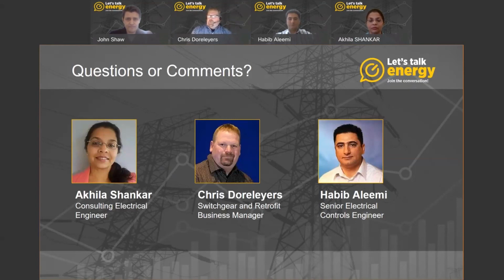So actually, there's a number of different things that need to be considered when integrating an energy storage system with, let's say, a conventional switchgear and power generation system, whether it's standby or prime. Energy storage systems are often coupled with the microgrid aspect as well.